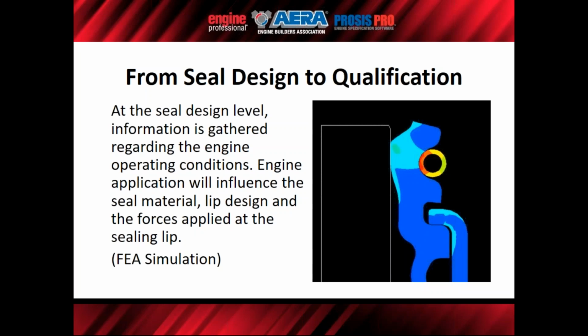So at the seal design level, information is gathered regarding the engine conditions. Engine application will influence the seal material, lip design, and the forces applied at the sealing lip. This is done at the finite element analysis point of the design. So much like you would do FEAs for fasteners for head lift, or what's going to be happening to a piston, or what's going to be happening with a valve, these same types of analysis are done in development of the valve stem seal.